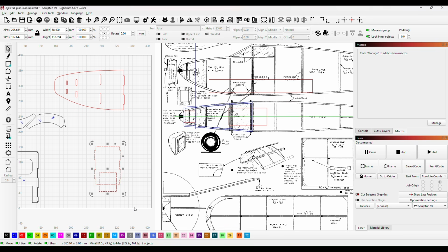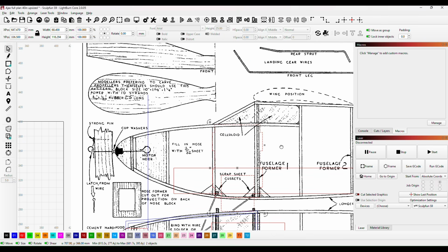And then if we grab them both, we won't group them, and we bring them across, I'll put that corner right back to the top where it needs to be, and then all I want to do is move this shape up until it reaches the line that we decided would be the depth coming from the bottom, or the height of our hatch for our battery.